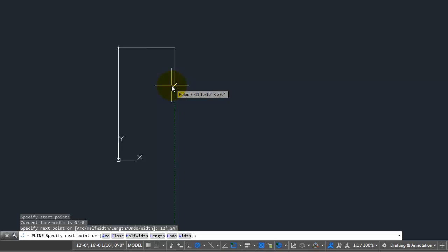Okay? And relative coordinates say, instead of referencing point 0, 0 as the origin, it's going to be whatever your last point was that's going to be the starting point. So if I started out here, and in absolute coordinates this was 0.6, 6, remember? If I did relative coordinates, I could specify, and the way we do this is we put the little @ sign, like the email address sign. So we say at, and then I'm going to give the coordinates.